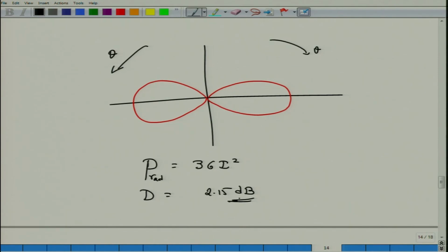This antenna pattern has its maximum value at theta equal to 90. At theta equal to 0, you do not actually have any power, and this antenna pattern is much better approximated by the donut than the previous elementary dipole antenna.